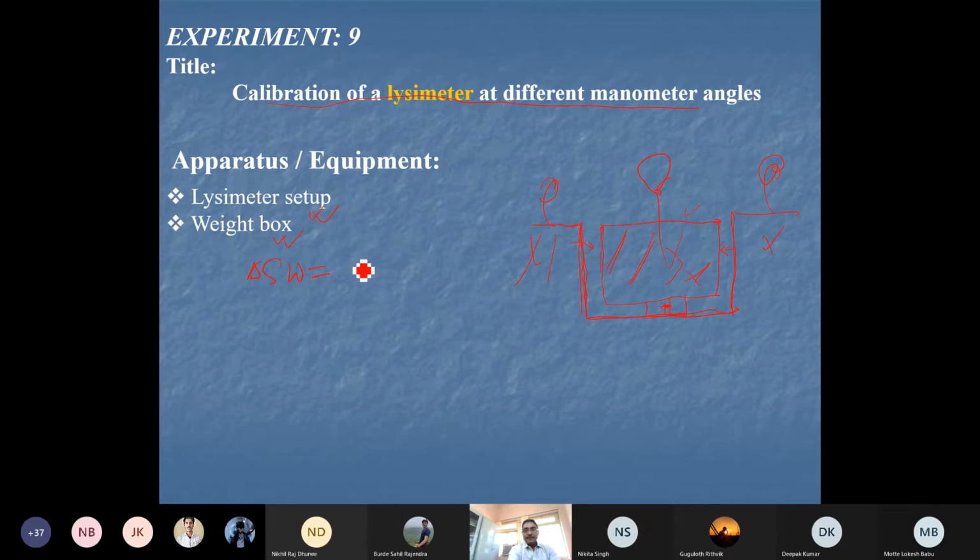It is basically any irrigation we are adding, any rainfall that has occurred, then minus any drainage loss, minus ET, that is loss, and minus any runoff if there is any. This is rainfall and this is runoff. So addition is irrigation and rainfall. Negation means going out as moisture. So drainage, it could be at the bottom. It could be ET, that is lost from this area, or if it is excess water, that is runoff that has been generated from this area.